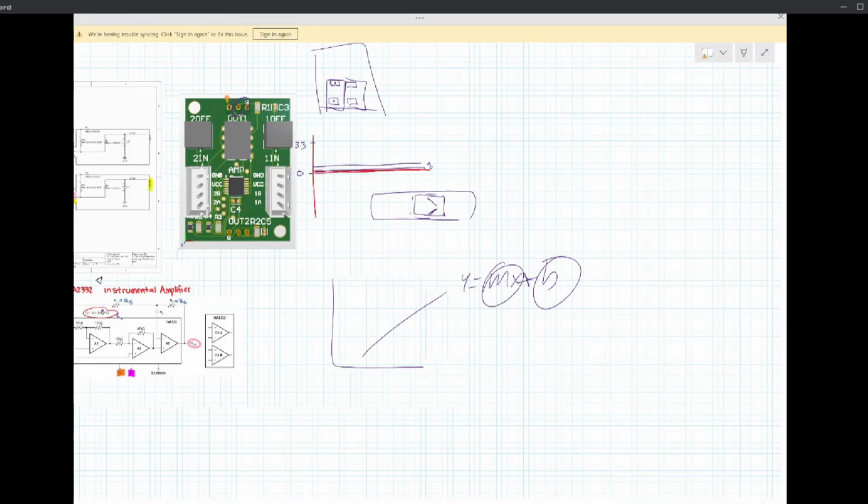We have a couple funny setups for that. For bending, for the most part, you just hold one end in like a vise or something, and then you progressively add more and more weight on the other side, and then you see what the voltage output is on the oscilloscope.